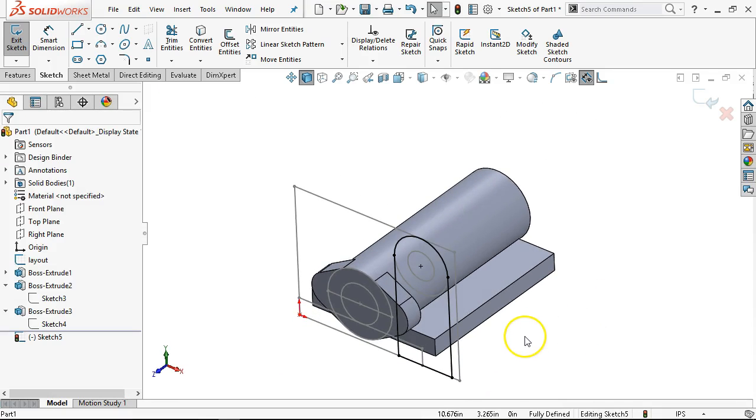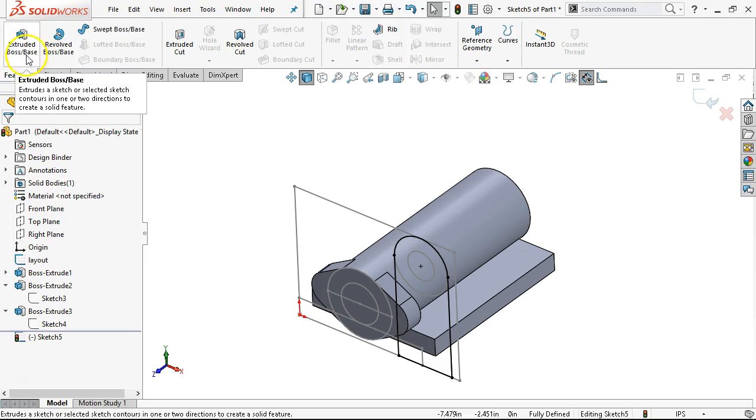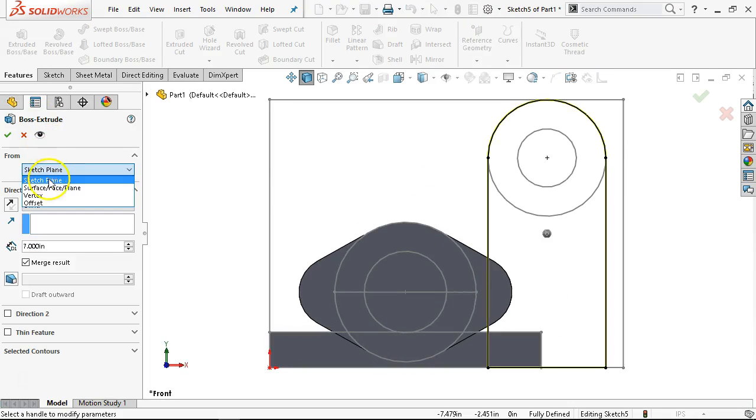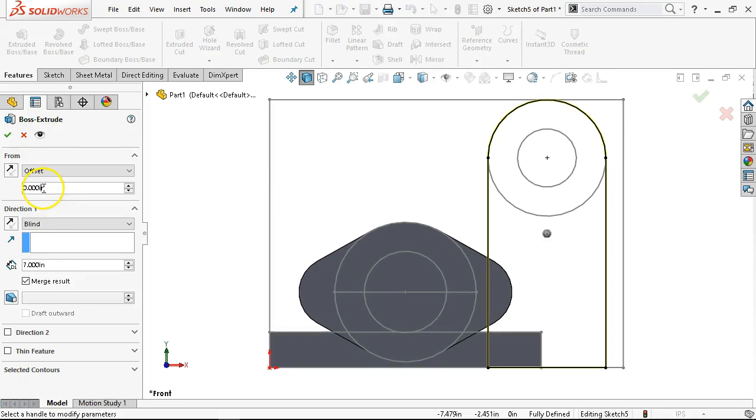Alright, so to the center of the boss is, double check that, 4.76, and then we're 3 inches either side of that dimension. So that stack up, extrude, we have a starting plane that is offset.